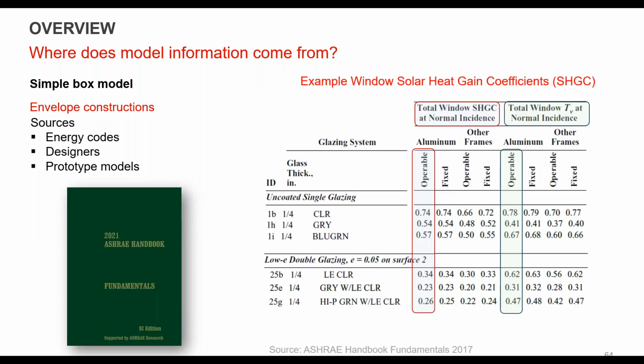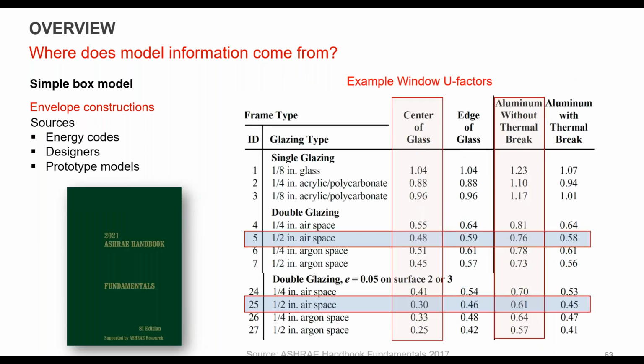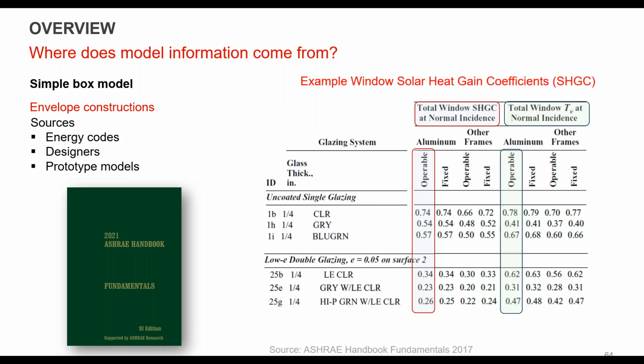So again, for some of the older buildings, looking at the ASHRAE Handbook Fundamentals might be a place where you're going back. If you know you have an old building with single pane glass, you might be looking there to find what your U factors are. There's not a great data set for that. So a lot of times, I'd say Fundamentals is a good spot.